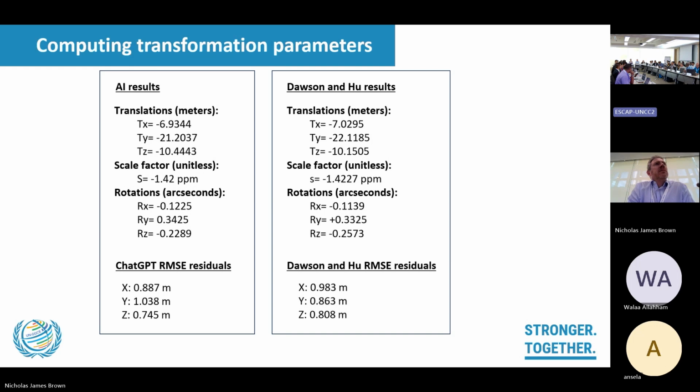The other point you raised was about ellipsoid heights. Now, obviously, with an old datum, you might not have ellipsoid heights. They might be just orthometric from whatever technique was used. So we did the PNG transformation from AGD 66 to PNG 94 using a similar approach. But because we didn't have ellipsoid heights on the old system, we just fed them the same ellipsoid heights as what the GPS had observed. So we basically took that element out of the inversion, simply because we didn't know what the ellipsoid heights were.